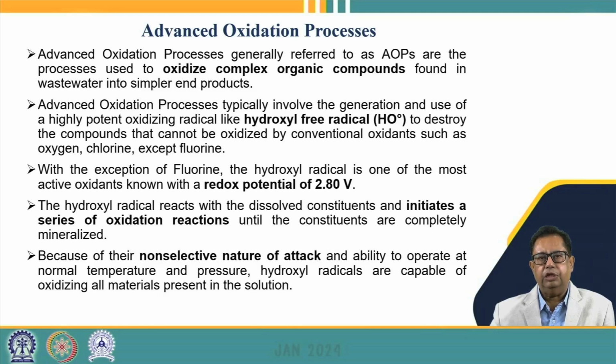So because of the non-selective nature of the attack and their ability to operate at normal temperature and pressure, hydroxyl radicals are capable of oxidizing all the materials which are present in the solution. So if there are certain compounds present in the wastewater matrix, we can have compounds which cause BOD, compounds which cause COD in the wastewater, and similarly pharmaceutical compounds present in the wastewater.